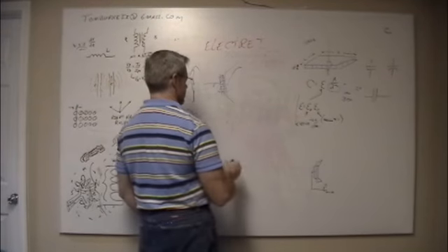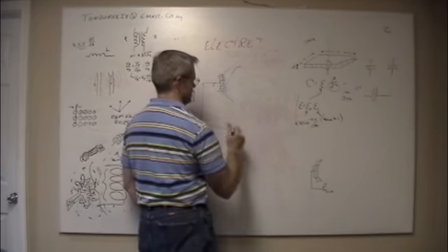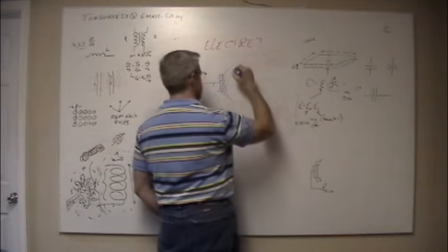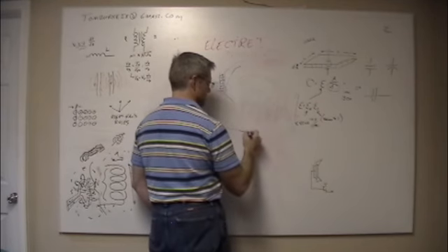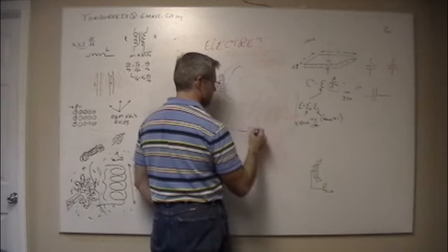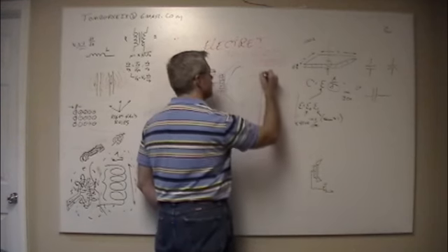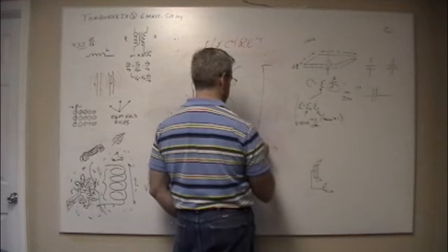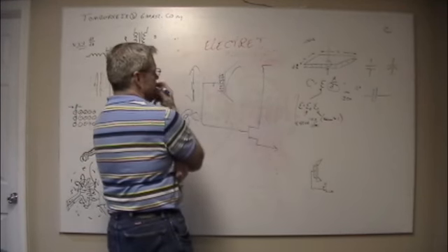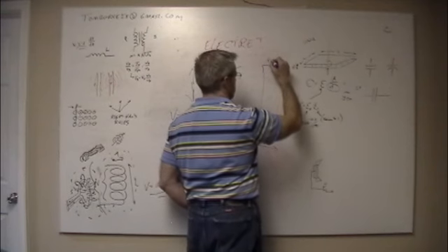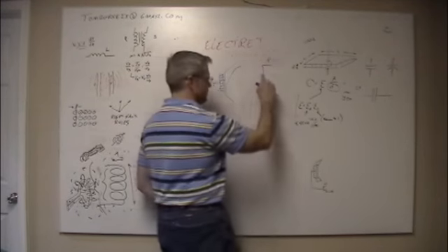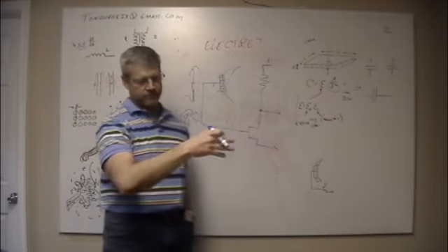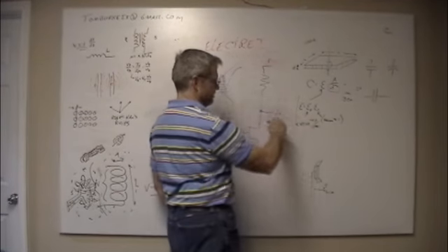And the Electret microphone has 3 inputs. Have 3 inputs? Yeah, it has a FET in here, a JFET usually. So here's your 3 inputs. Just 2, what's a third? You've got power. Oh, it has 2. Some of them have the third built in. So there's a resistor in here, and that might be the third output, depending. Some are only 2, and you have to put this resistor in yourself and take your own output.